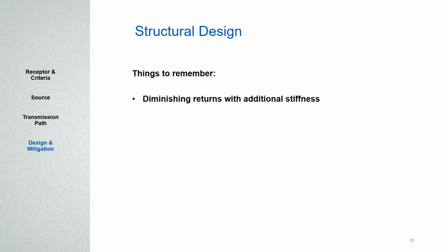But once you get to very, very stiff floors, like once you've got very large beams underneath your floor, going to the next larger beam doesn't do you too much. In fact, I found that often the increase in the stiffness isn't the thing that's helping you. It's that you're going to a heavier and heavier beam, and it's the additional mass of the beam that helps you out the most because it's harder to move a larger mass.